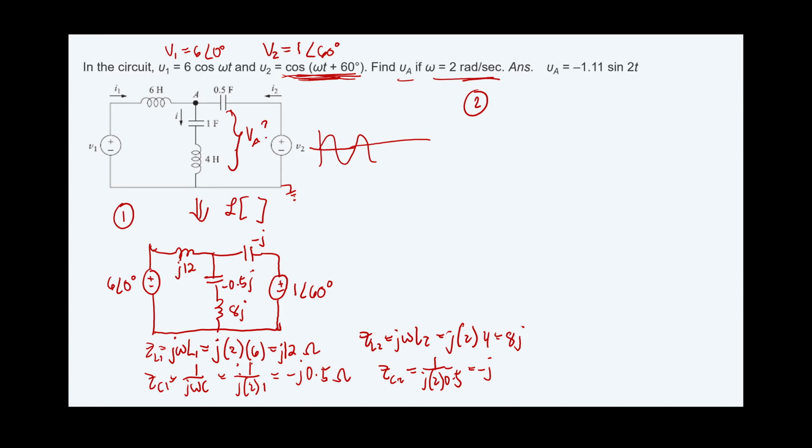So how do we solve that one? You might wonder, we can use mesh analysis, which is okay, or you can use the nodal analysis, because you can see that the value here is V2, then the value here is V1. Okay, so if your ground is here, so V is equal to 0, therefore here is V2. Given the polarity, you have V1 here. Okay, so therefore you can construct like this.